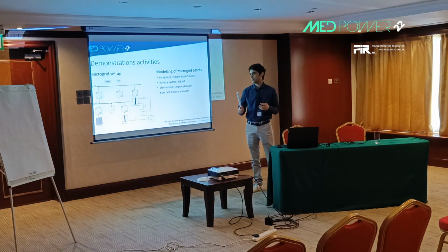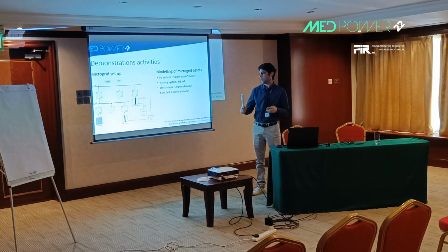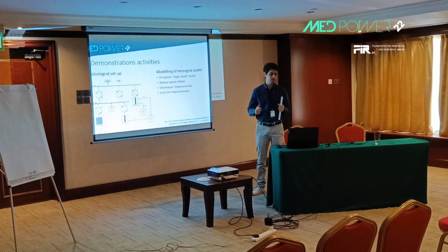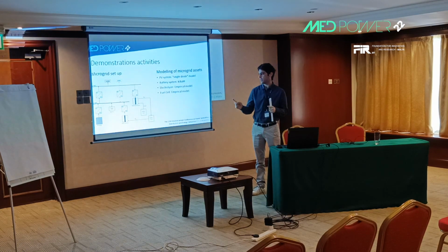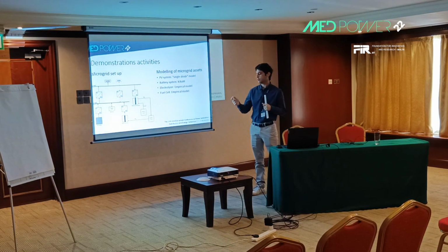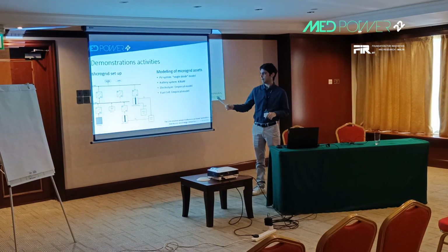It is constructed based on a DC bus architecture. It consists of a PV system and several flexibility elements such as a battery system, a power-to-gas system consisting of an electrolyzer, a fuel cell, and a hydrogen storage tank, and some flexible loads. In the context of the Efstratios project, an SMA Sunny Island inverter was installed in the microgrid to serve as an interface of the microgrid with the electricity network.